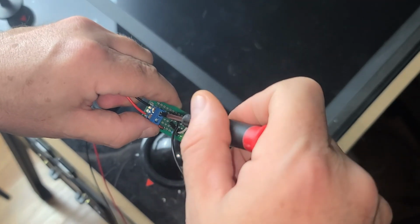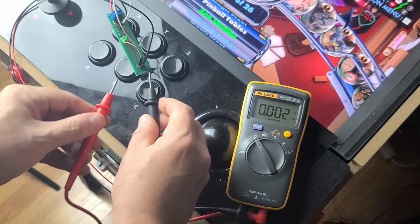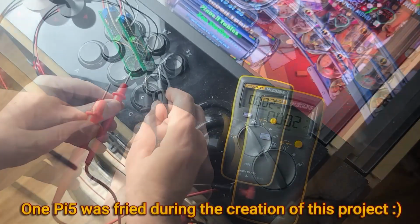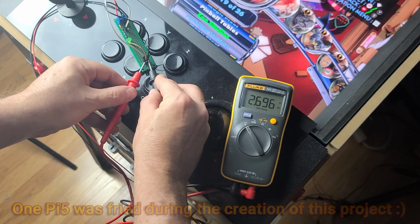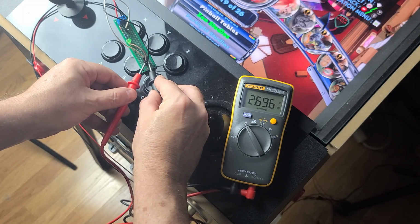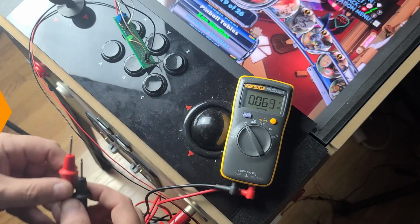power on the machine. Now I'll do a quick check of the voltage coming from the Legends 4KP to make sure I don't damage the Raspberry Pi 5 GPIO chip. The voltage the Pi can handle is around 3.3 volts, and we're at a safe level at around 2.7 volts.